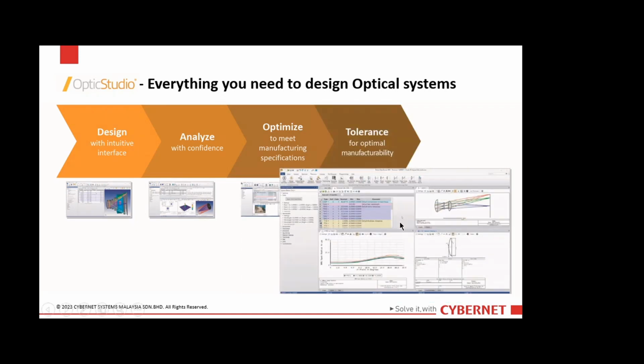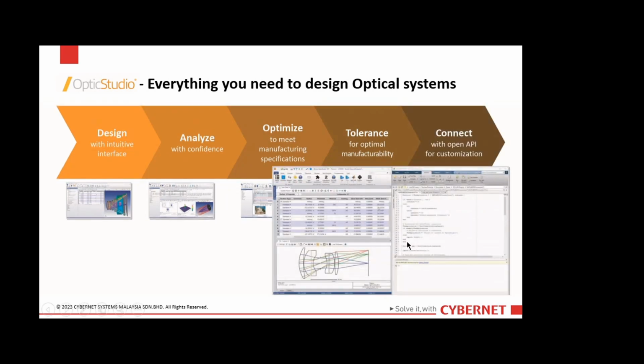After we optimize, we go back to analyze again and check whether it meets the specification. Before manufacturing, we go to the tolerancing. We set the tolerance and offset, to see if the system has a manufacturing error or offset, is there any effect on the output? Lastly is the connection with macros. We have coding, and we can use macros, the ZOS API, to optimize the design. If the analysis is done regularly or repeatedly, we can use a macro to run it automatically.